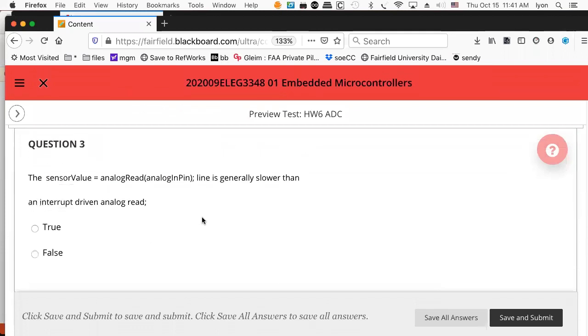And then here's a sensor value coming in from an analog read line. The interrupt-driven stuff that we've done is way faster, right? I mean, we've seen that. We took the prescaler, we cranked it up to 1 megahertz, we got 76 kilohertz sampling. This thing with this analog read is going to go about 1 sample every 115 microseconds, which is, I don't know how slow that is.